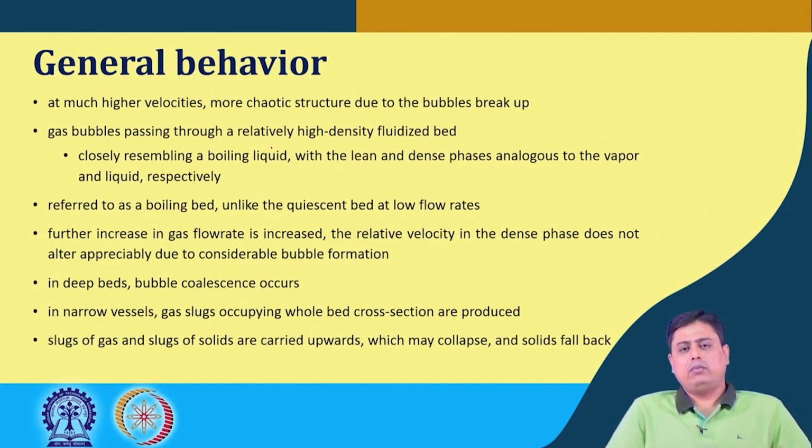Unlike that, in the case of a low flow rate, there is a stagnant bed and some gaseous phase is flowing through the bed. Okay, there is a calm and quiescent bed at low flow rates, but at very high flow rate, this bed will behave as if it is a boiling bed.